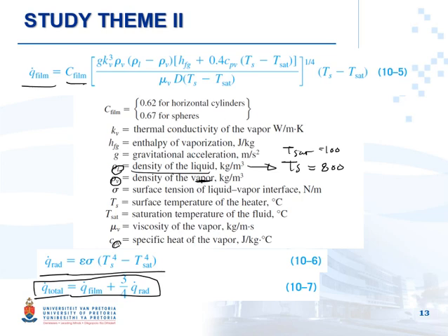It's very important to know that the vapor properties, when we are talking about film boiling, should be evaluated at film temperature. So vapor at film temperature.